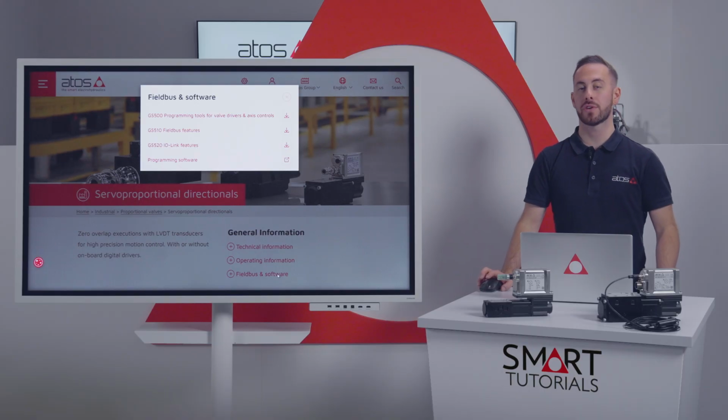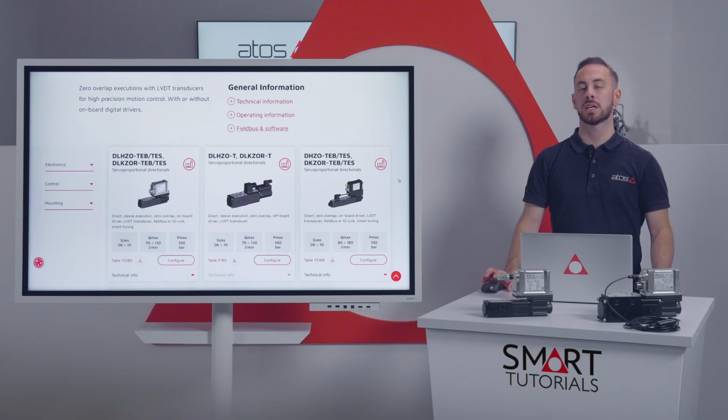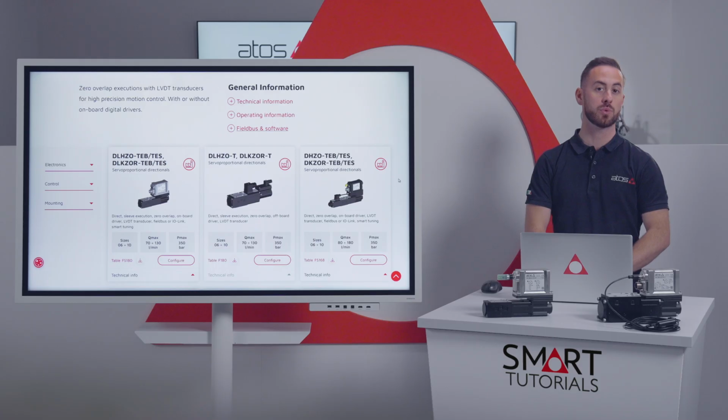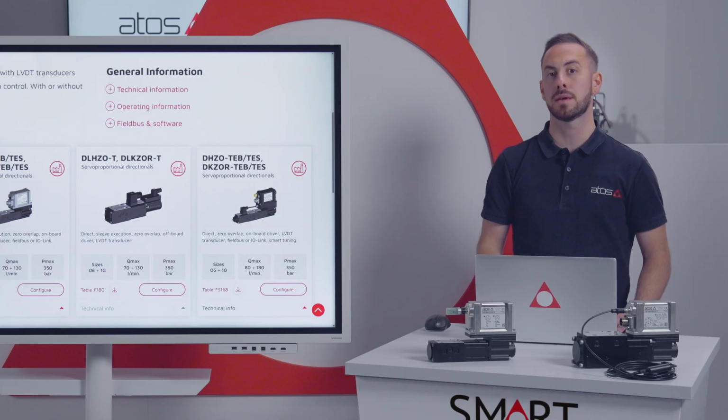If you want to get more information on how to download and install the Atos programming software, please watch the related video on our channel. One of the first things to verify during a connection issue is that the valve or the driver is correctly powered on. It may seem obvious, but trust me, many of the connection issue reports we receive are caused by this aspect. Therefore, as a first step, always be sure that the driver is correctly powered on.